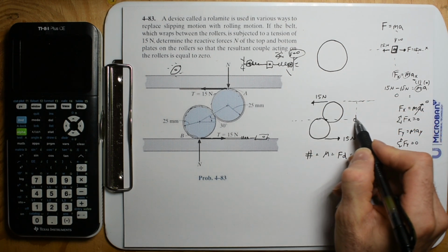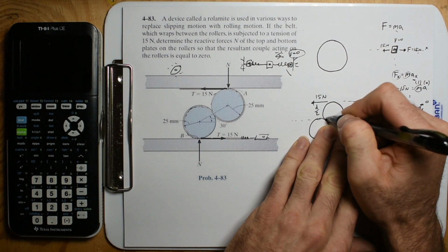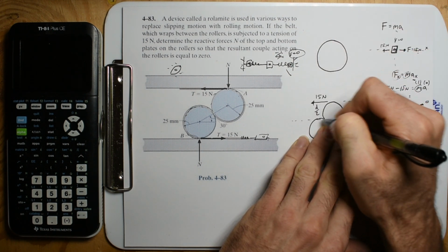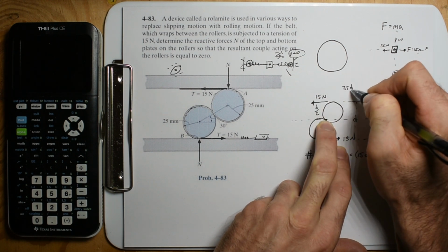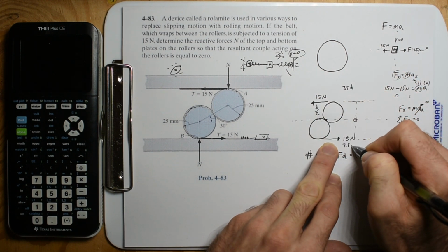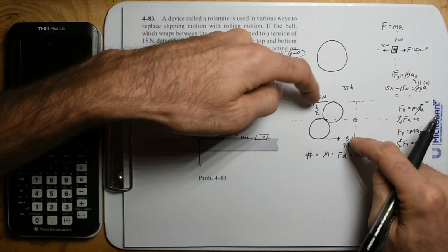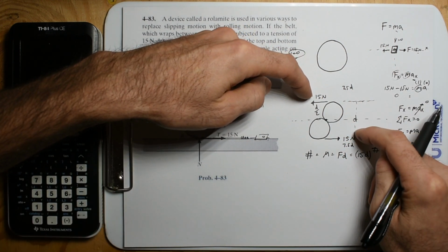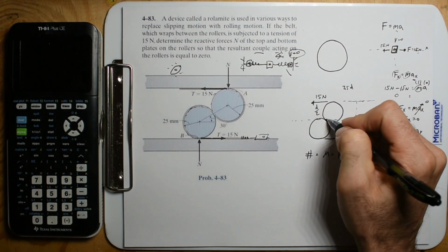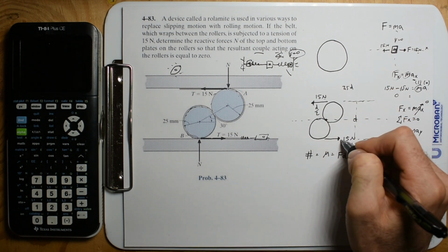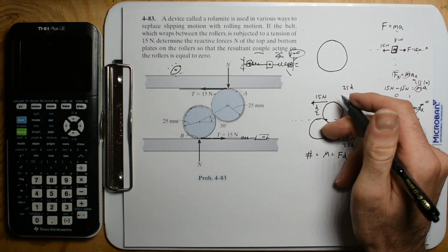Now, you might be familiar with just taking one at a time, and you would say this is d divided by 2. So we would have a moment from this point of 7.5d, and then this one is 7.5d. Those are going to add to 15. That's why if you have two identical forces separated by a distance, this is called a couple. Now, it's still a moment. You can still just sum them up, as this is a force times a distance, and this is a force times a distance.